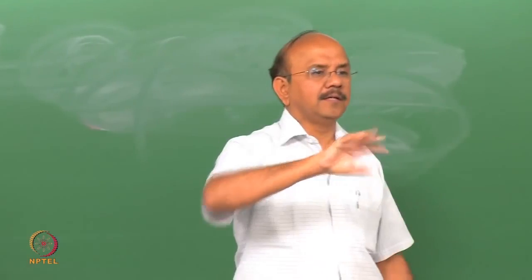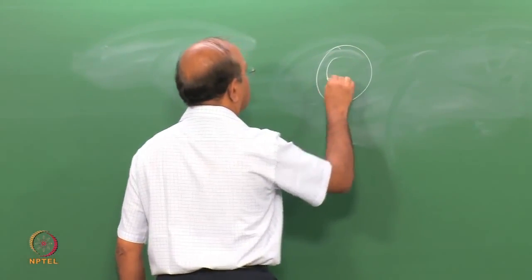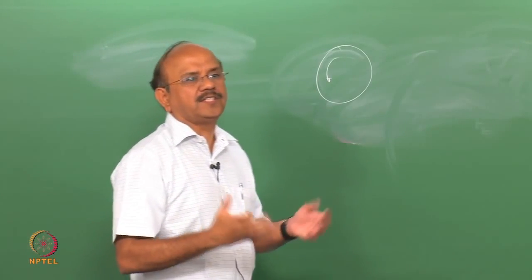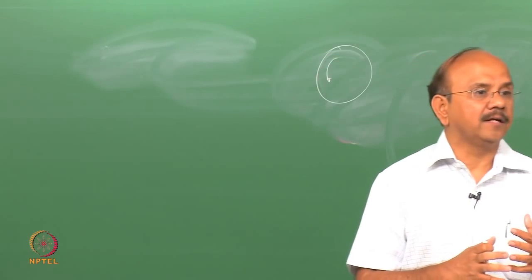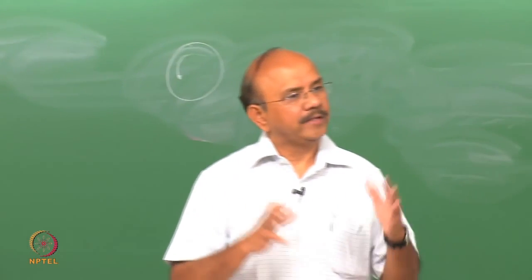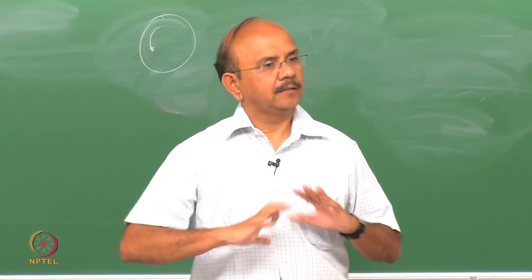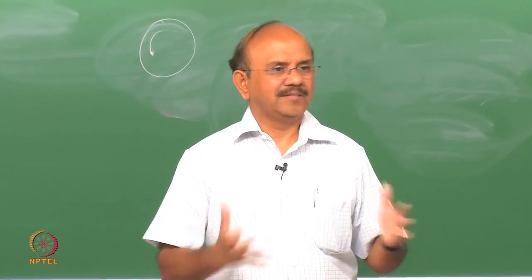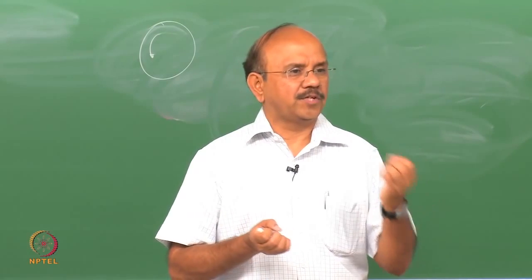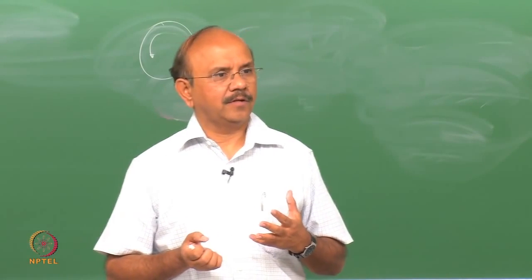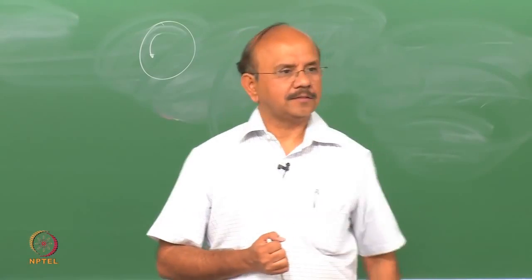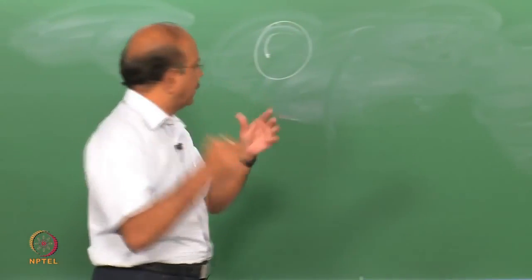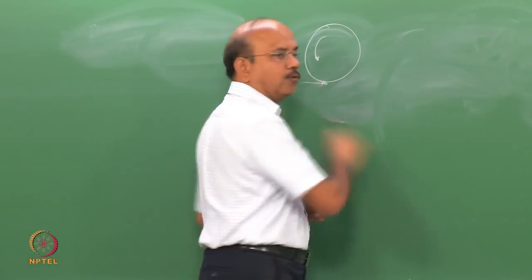I am rolling it like this. The rolling resistance doesn't care whether you are actually accelerating, decelerating, or doing neither of the two and traveling at the same velocity. It doesn't matter to it. As long as there is compression and relaxation, and we are going into the viscoelastic effect, that will give the rolling resistance, right? So, in either case, you will have that force here.